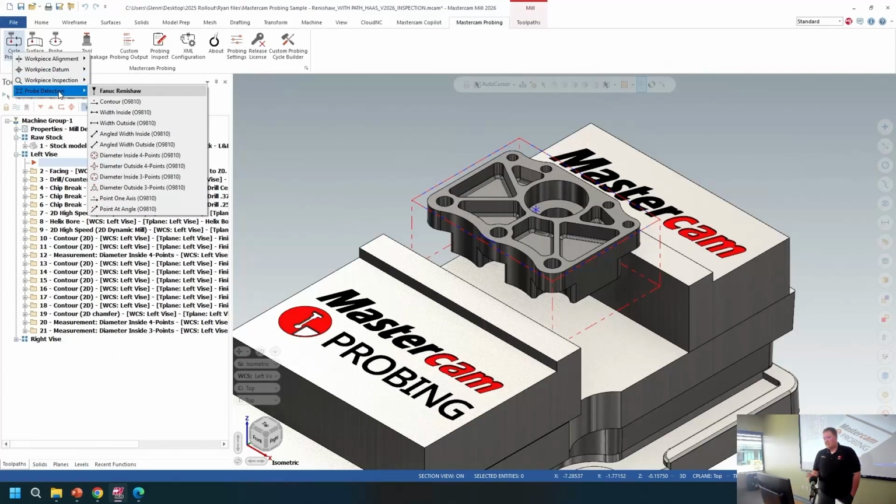So probe detection is kind of unique in the sense where when the probe is moving around, we have a protected safety move. And that way if the stylus were to be tripped, we're going to stop the machine without crashing it. And so you could check a part orientation. You could check to see if a toe clamp's been removed before sending a cutter through. Again, a number of different ways you could do that in order to achieve more automation and less hands-on with the operator.